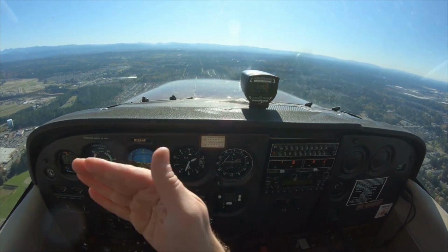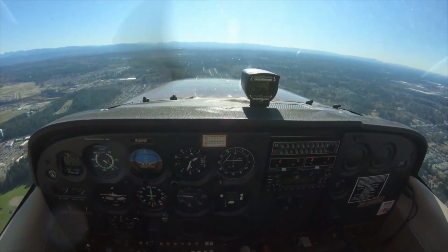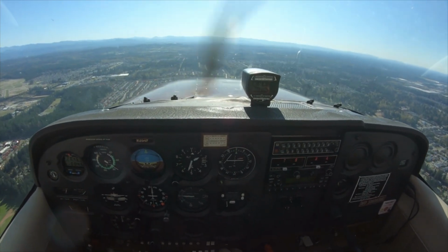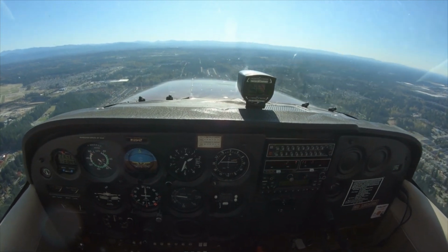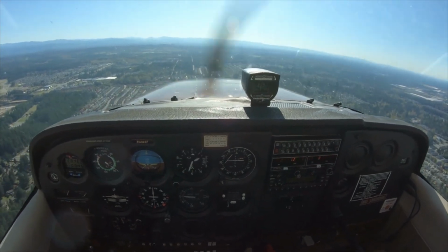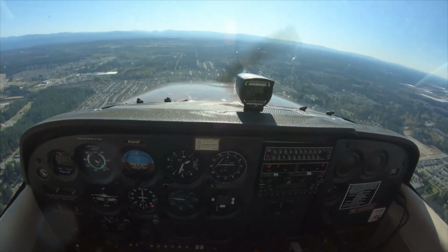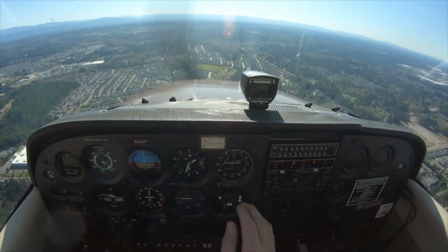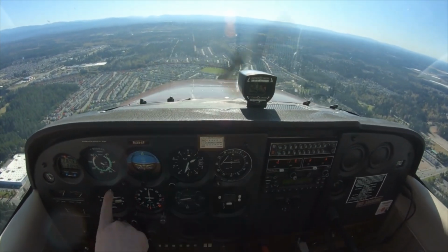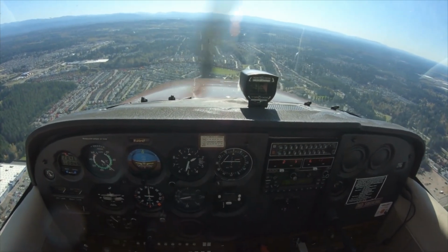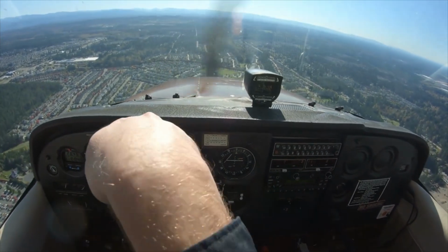Because the final approach over obstacles is made at a relatively steep approach angle and close to the airplane's stalling speed, the initiation of the round out or flare needs to be judged accurately to avoid flying into the ground or stalling prematurely and sinking rapidly. A lack of floating during the flare with sufficient control to touch down properly is verification that the approach speed was correct.